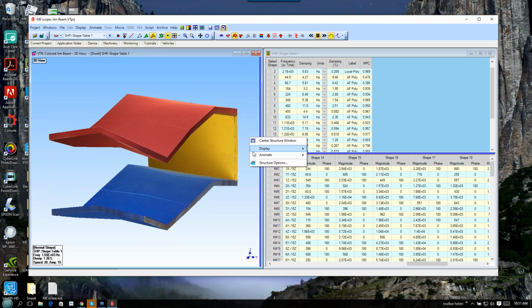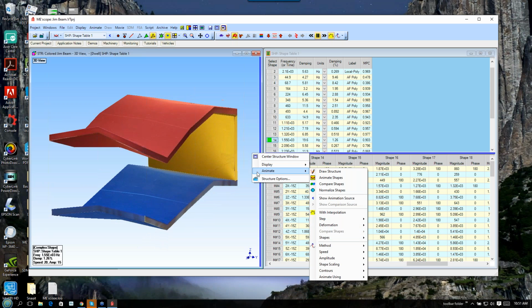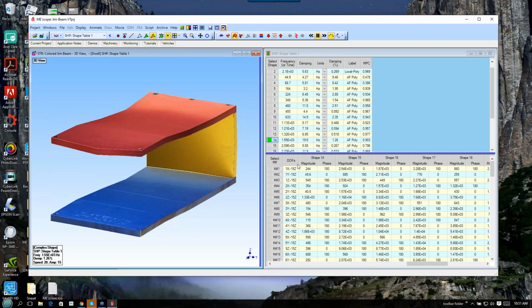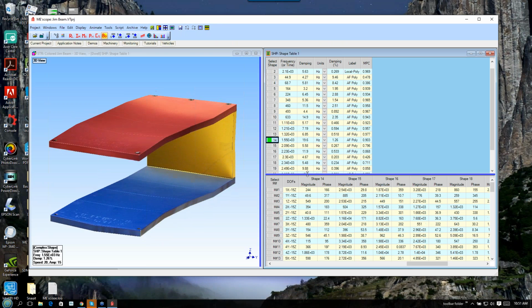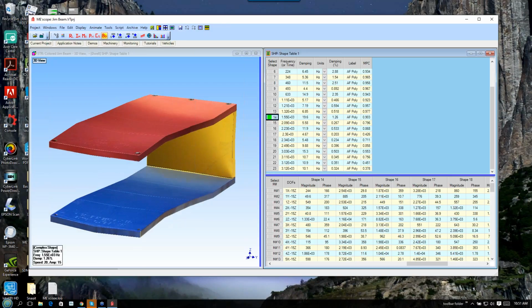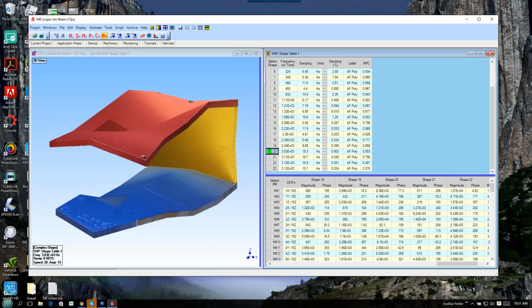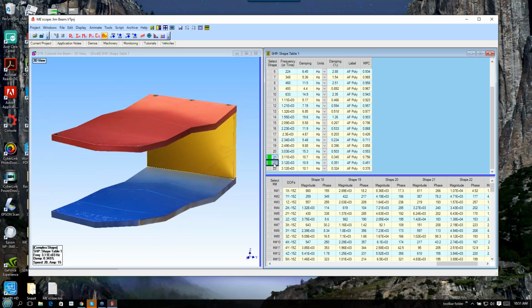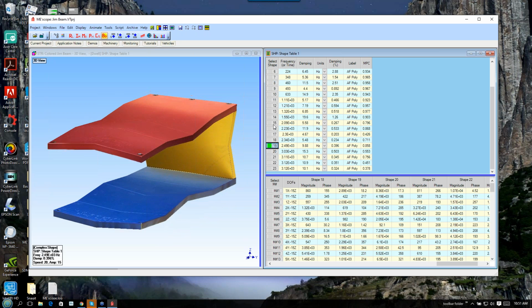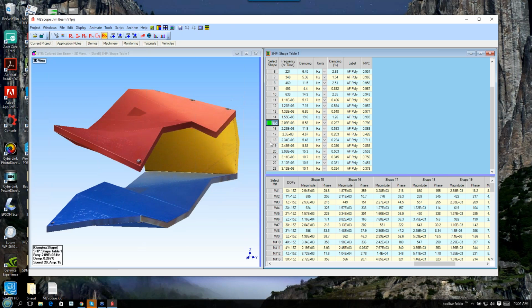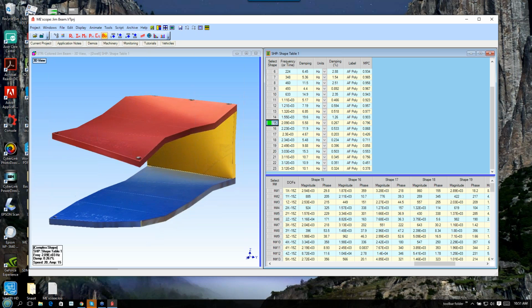If I turn it off, you'll see that it goes back to, well, come on. It didn't update my display for me. Okay, there we go. So if I click now on these mode shapes, you can see the phases are not 0 and 180 anymore for these high frequency modes where the mass loading effects were the greatest. Let's go to the 2 kilohertz mode that we did the local fit on before. You can see phases are all over the place.